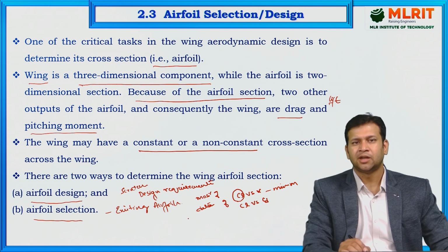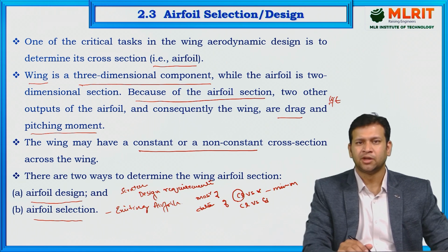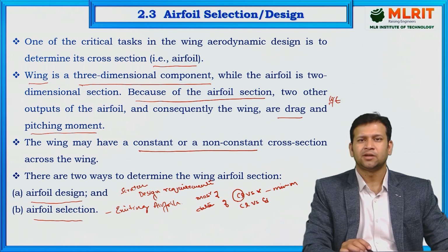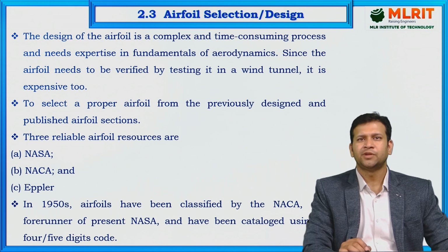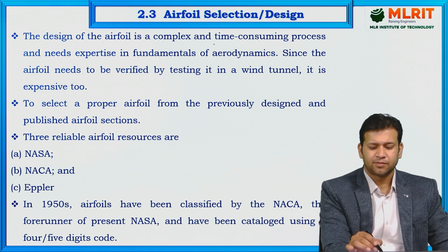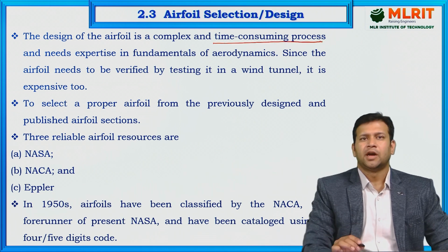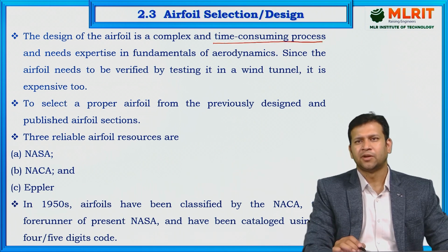If we have to design our own airfoil, first we have to do it numerically, then we need to test the airfoil in the wind tunnel to get the real-time test data, and these test data will again be validated with computational studies. The design of the airfoil is a complex and time-consuming process and needs expertise in the fundamentals of aerodynamics. Since the airfoil needs to be verified by testing it in a wind tunnel, it is expensive too.